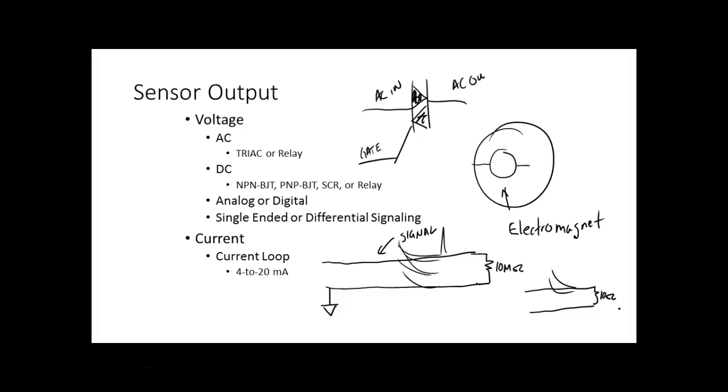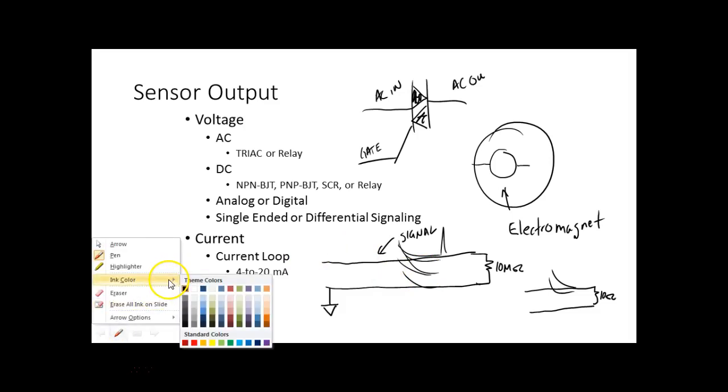So this was single-ended. Single-ended is when you reference one of your conductors to what? To common, and then you have the other conductor that has a signal wire. This single-ended was pretty susceptible to electromagnetic interference. So what they did, and this is what just about all our communication standards use right now, USB, Ethernet, just about all of them, the telephone system is actually the first one that came up with this interface, by the way, to reduce noise.